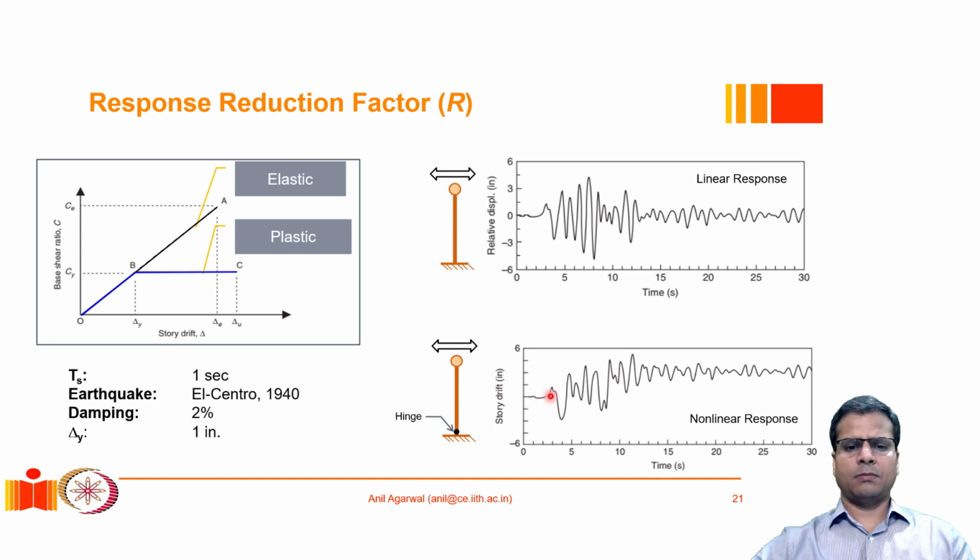and again the displacement at the top is measured. So one thing obviously we can see is that in the linear system we were getting a net zero displacement at the end, because the system was coming back to the zero position after the earthquake loading was completed. In a plastic system, however, there is a residual displacement. After the earthquake history has completed, there is a leftover displacement in the system, which is expected because the system has a plastic deformation, which is a permanent deformation.